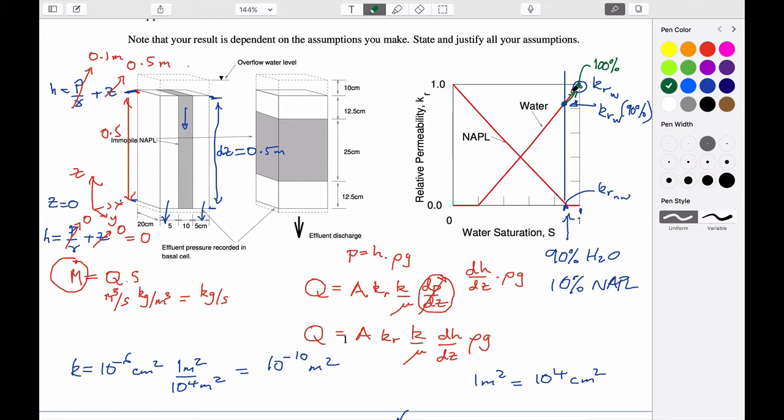So we spent a lot of time talking about swimming pools, and why there was this extra term in addition to pressure, which is the static head sitting on its own. We also talked about the way to get around that, which is to make the substitution that we made here: don't deal with behavior in terms of pressures, but in terms of heads. If you deal with it in terms of heads, you'll always be right. This expression isn't quite right with just this one term. It needs an extra term, because when we sit in a swimming pool, there's a pressure gradient with depth, but that's not moving anywhere. It's just a static pressure gradient. And so we need to incorporate that other term.